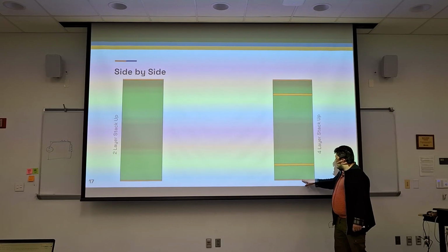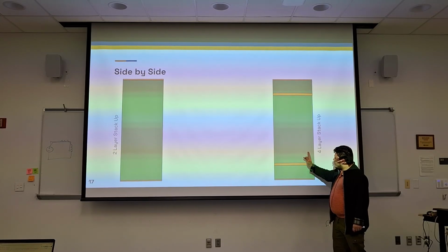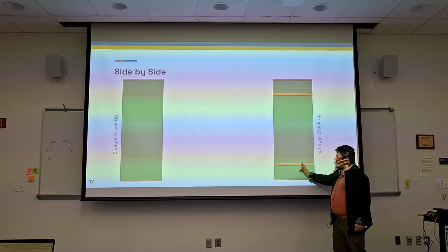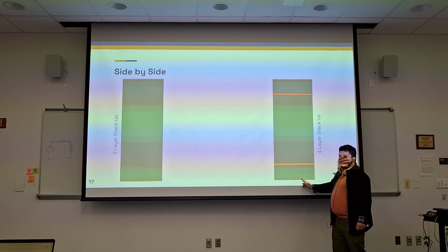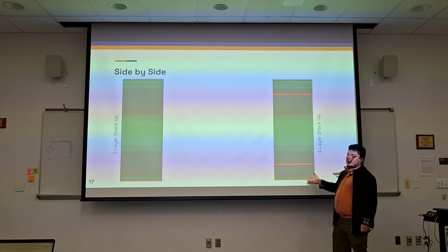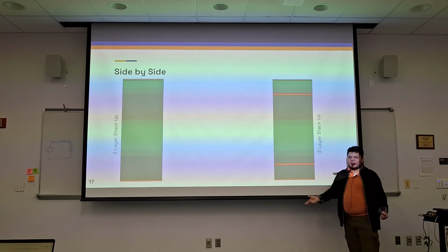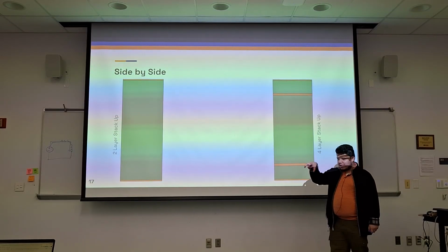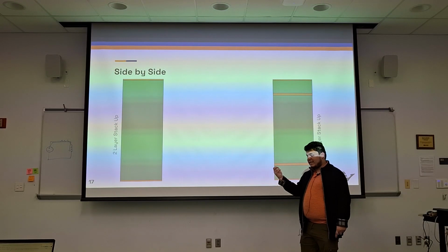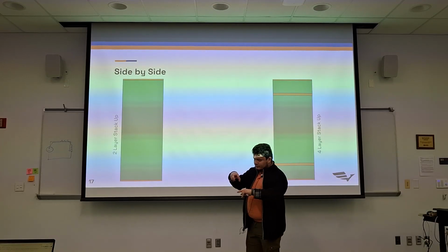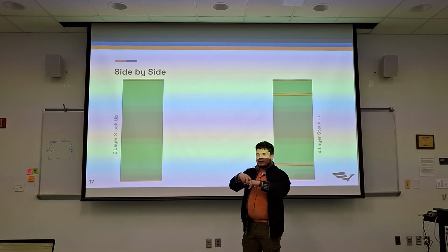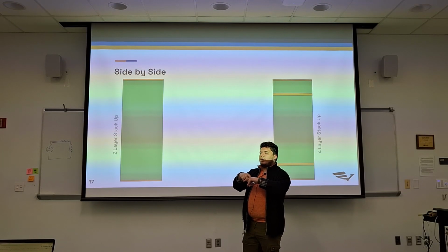And so ideally you would have a ground via that goes in, that taps into your ground. And so your ground reference would connect through a via. So any connection is done through a via or any through hole, right? Because you can have a connector. I guess I didn't talk about this, but you can have a connector that is through hole, but you do not have to go in from the very top.